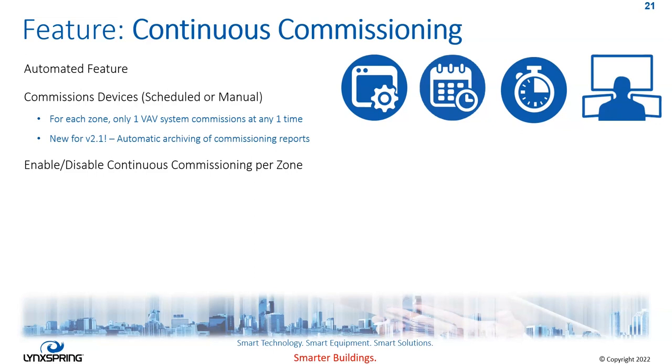I will actually disable the continuous commissioning process during the summer because I don't necessarily want to turn on my electric heat. Some customers will not be very happy about that bill that they see. You also can set up for an automated configuration, so it will do the whole thing automatically.